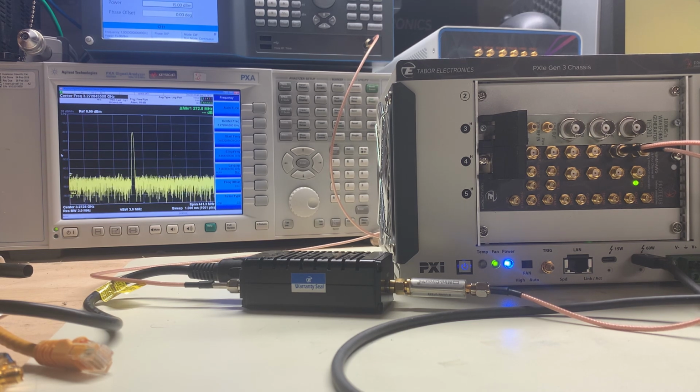So you can see we get this super slow linear FM, and to do this with regular techniques within an arbitrary waveform generator, it would literally take billions and billions of points to get this kind of slow frequency sweep. So it's a good demonstration of how real-time streaming allows you to achieve things you could probably only achieve with an analog signal generator. We can do this now with an arbitrary waveform generator and the real-time streaming functionality.